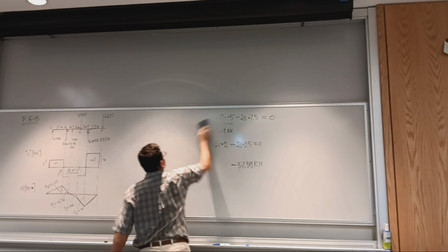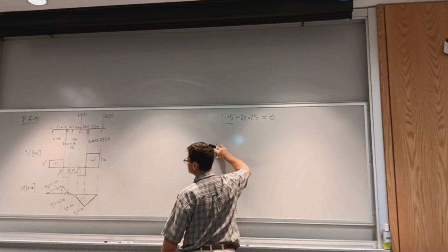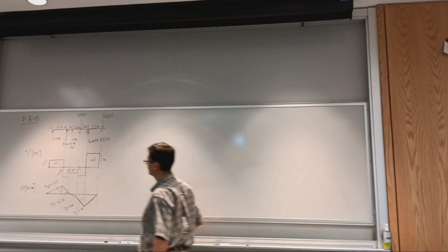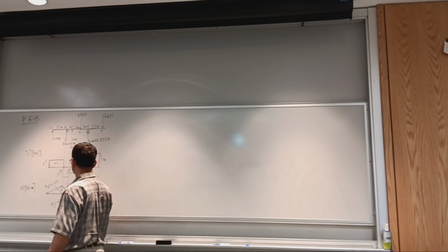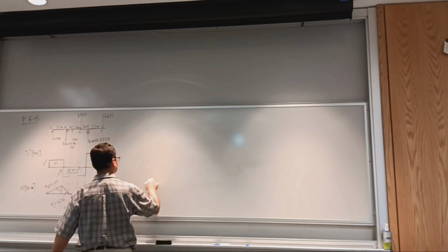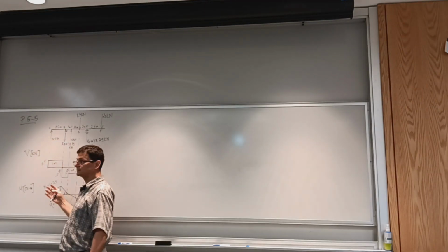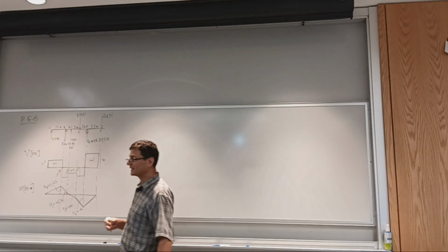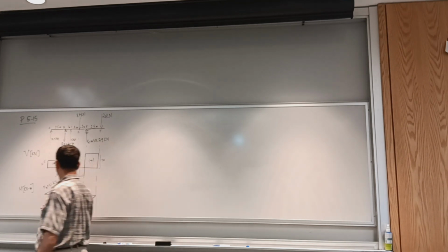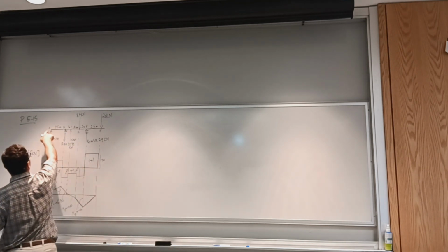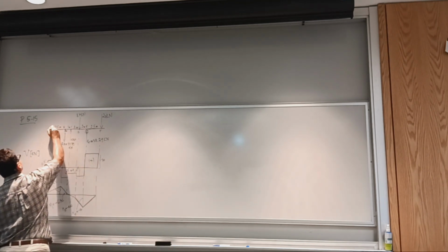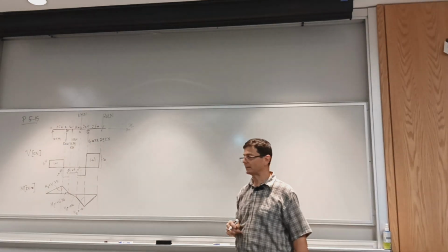If not, you can write the equation of the moment line for that portion. We did it before, and set the moment equal to 0 and solve for x, and it gets you where along from the end of the beam. Again, you define the origin here and have an x-axis along the beam to the right.